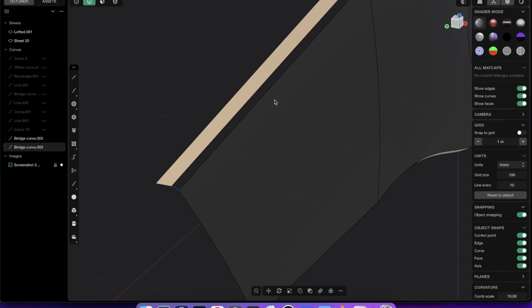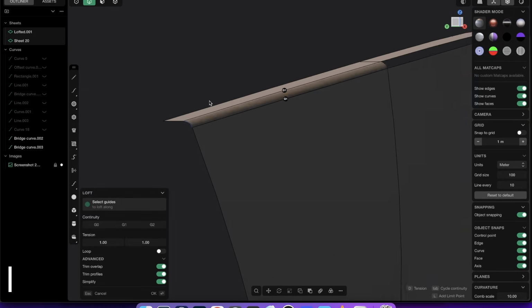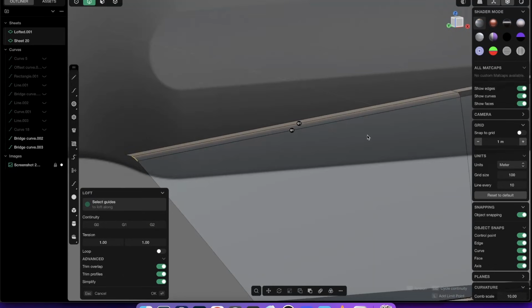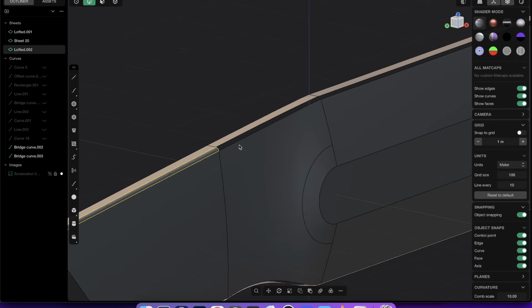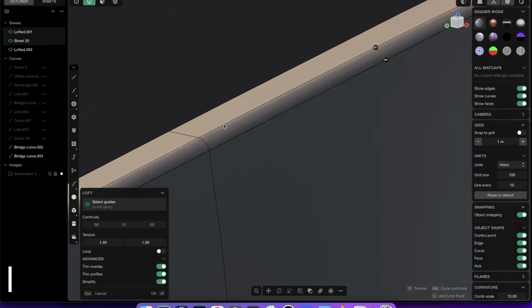Because now again, if you press 2 edge mode and you select those two edges and L loft it, with shift click you can add it now as a boundary to this curve, and now you see it looks perfect. Right click and let me hide that image in the background. So like that. And now you just go to the next one, shift and loft. And very important, click here again so it's connected.